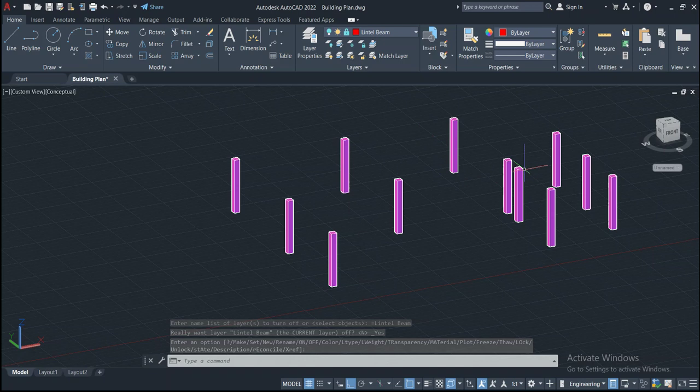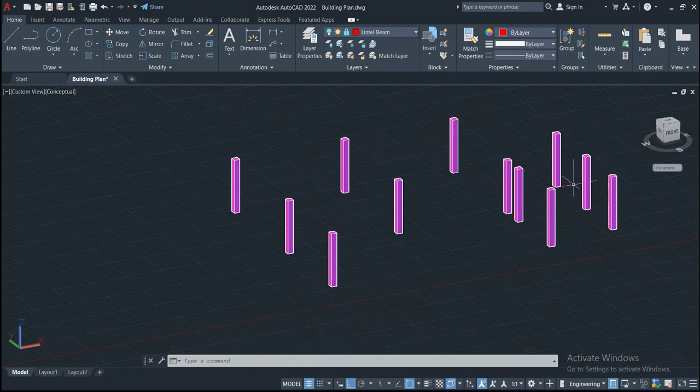Now we will proceed to extrude the columns to a height which should be 1 feet above the slab or roof level. So now it has a height of 7 feet. We'll add 3 feet to reach to the ceiling level, and then a 6-inch thick slab, so 3.5, and so 1 feet above the roof level, so a total height to be extruded is 4.5 feet.